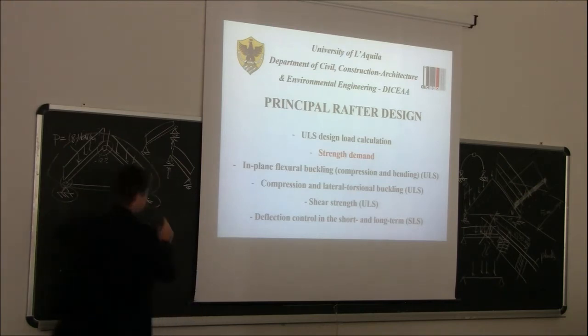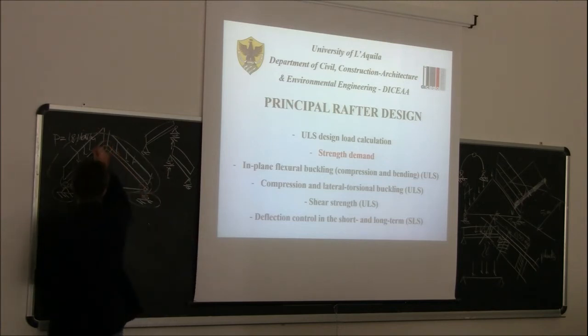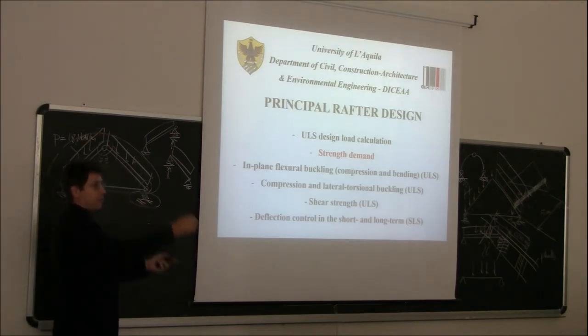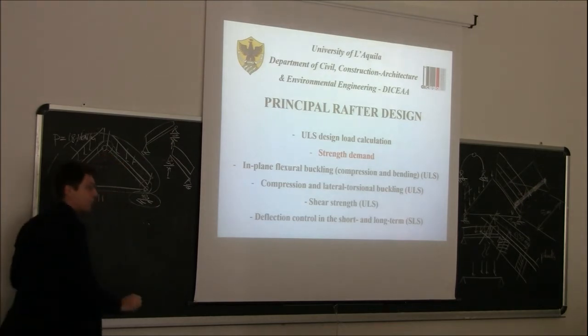So in order to go back to the original system, what do we need to do? We need to remove this restraint and apply the reaction changed by sign. So basically the opposite reaction. So I can say that the original system is equal to the superposition of two different systems.